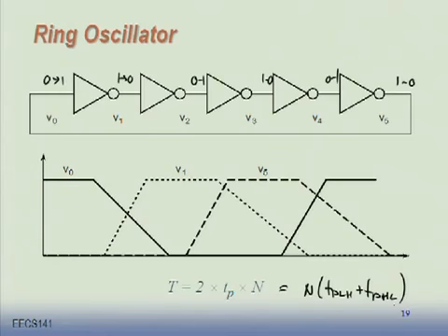Run your chip at the average frequency of those 2. How often is your chip going to be working correctly? 50% of the time, which is not usually what you want. What is the timing that you need to apply to that chip? The worst case, the worst of the 2.